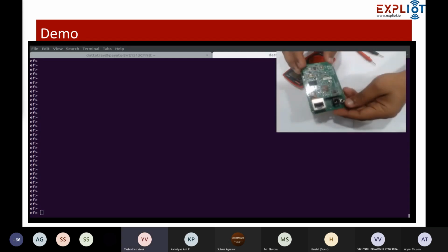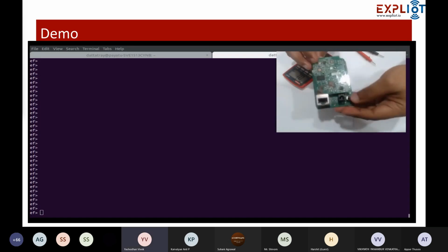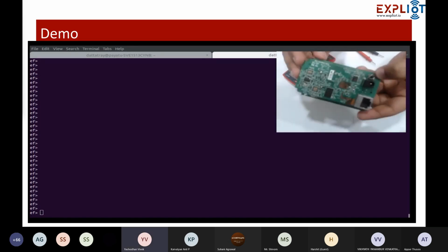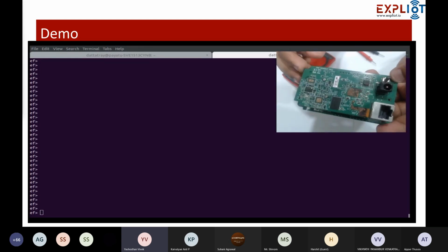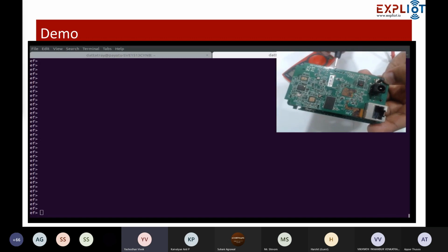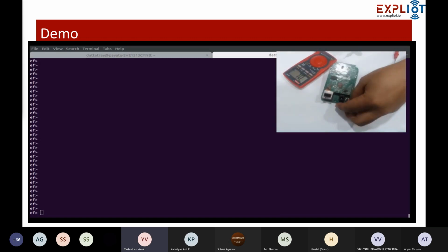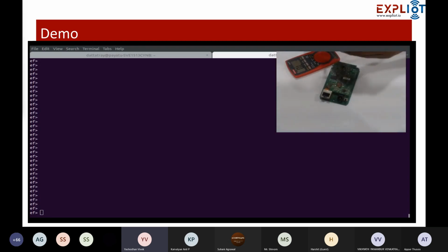Yeah. So this is basically a network-enabled camera, for which we had identified the pins of the UART. As you can see, there are 4 pins. Intuitively, it's a UART pin. Of course, we found the same thing. Now, our job is to identify each and every pin.